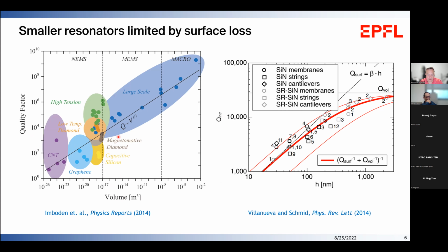And actually, over the last 15 years, these high stress resonators have had their quality factor increase by about 4 orders of magnitude. So this is this dissipation dilution effect that I talked about earlier. So this effect greatly increases the quality factors of flexural modes. So these are the violin modes, for example, of stressed mechanical resonators.